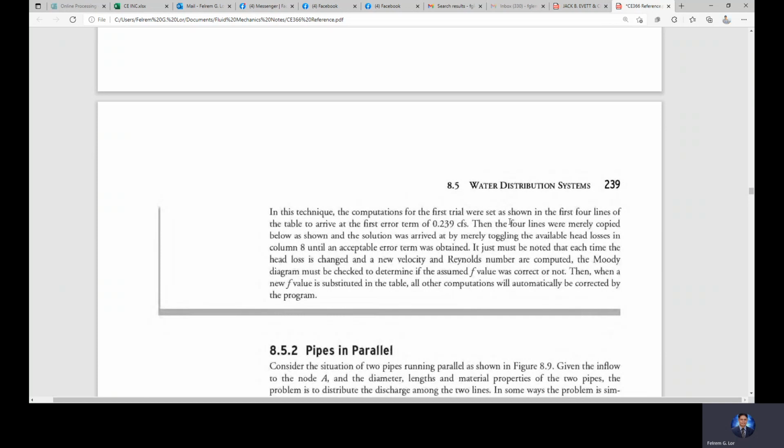For example, in our earthquake engineering, based on the code, there is the value of R, right? In earthquake design, R depends on the type. For us, it is given in the National Building Code of the Philippines, but in actual practice, if you study advanced earthquake engineering, it is solved. It is a long solution for the value of R. It depends on the type of framing and the framing construction material, and on the height from the ground to the upper portion of your frame.